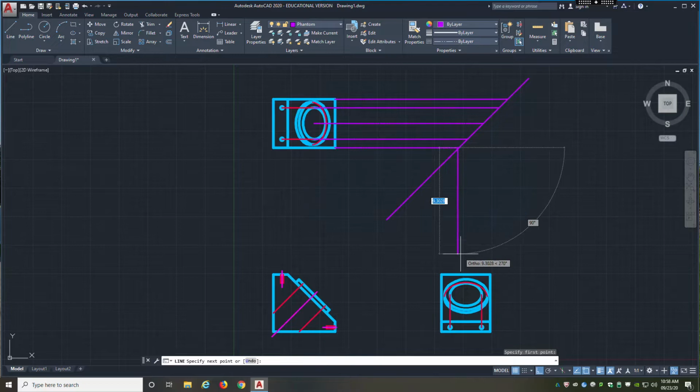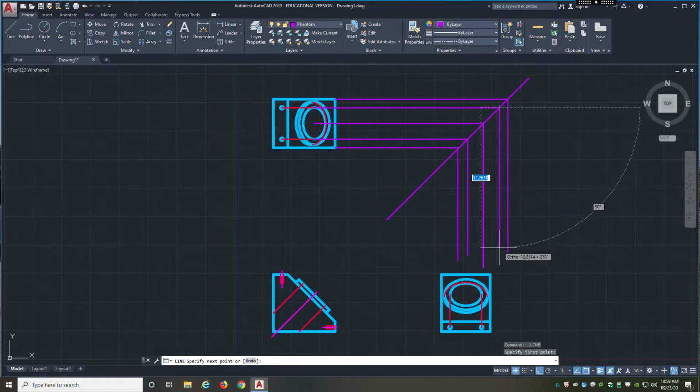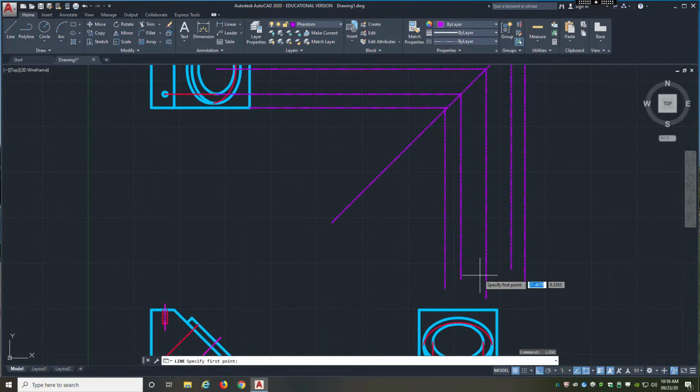Now this one is not lining up per se, okay? And the reason for that is that we arbitrarily drew our views, right? So I didn't equally space this right view from the top view. So that's why this is not lining up. But if you were to use the miter line method, then everything lines up. And you could draw your third view in this manner. So that would be the miter line method, okay, if you wanted to use that.